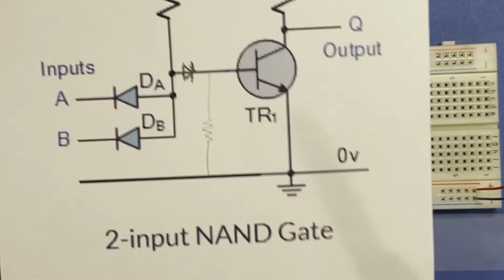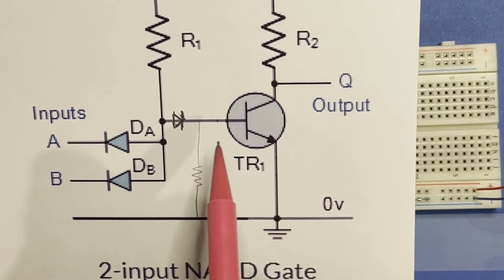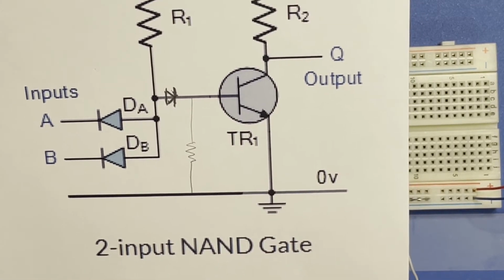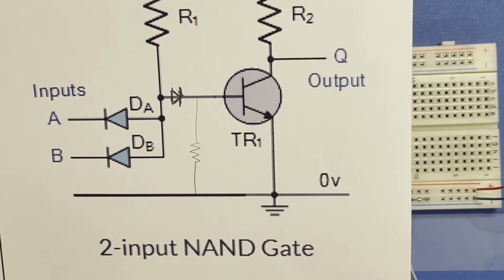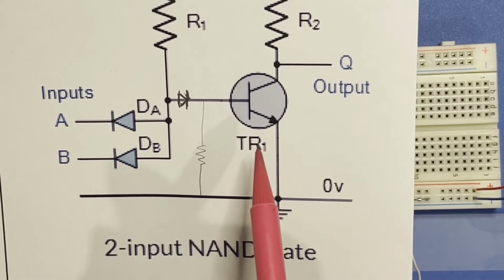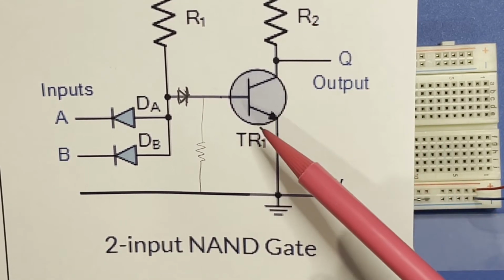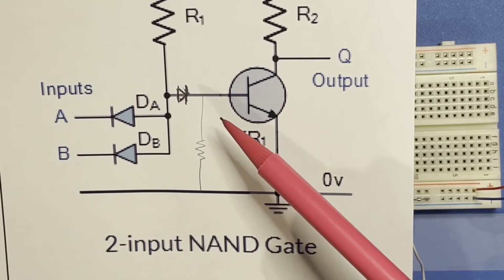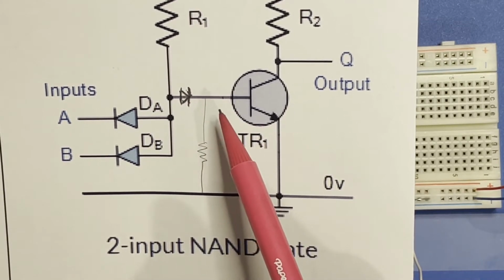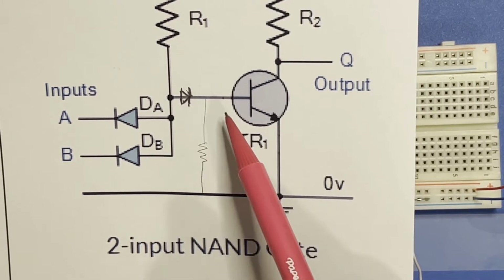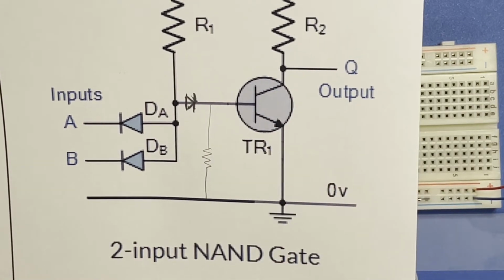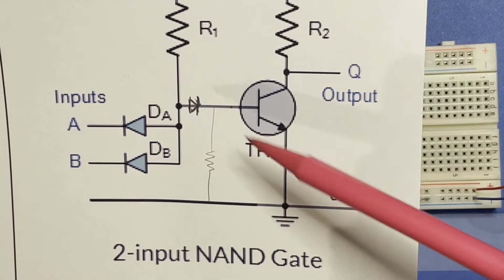I've got a resistor from the base to 0 volts to ensure that when there's no connection to the base, it does properly turn off. That's again something that's missing for a lot of hypothetical circuits or a lot of internet circuits generally. If a transistor's effectively open circuited on the base, any trace of leakage can put some voltage on the base and cause it to slightly conduct. So unless the input is being actively driven low or to 0 volts, you should always have a resistor. It can be quite a high value, but it should always have a resistor to bypass any leakage from the base or leakage from the circuit to drive it even.